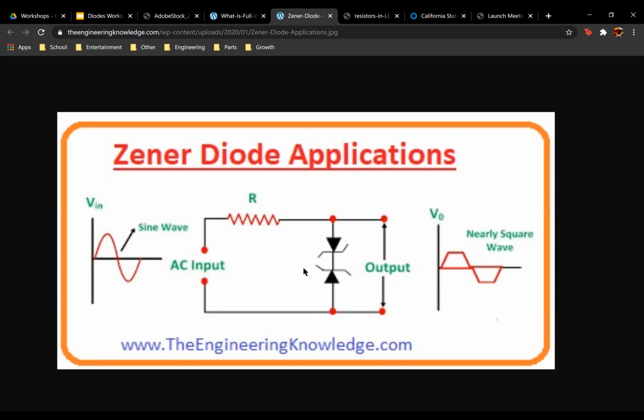And then in forward bias, diodes typically have a 0.65, would you say 0.6 voltage drop. So when they're oriented like this, either facing each other or facing away, the maximum amount of voltage across this part is going to be 8.6. You just have 8 plus 0.6.